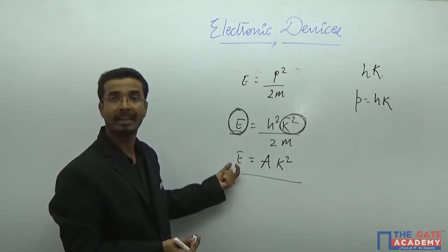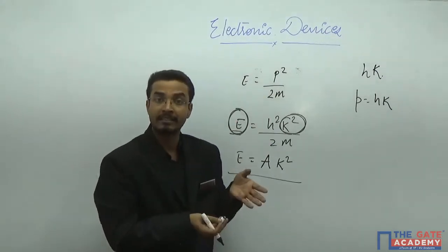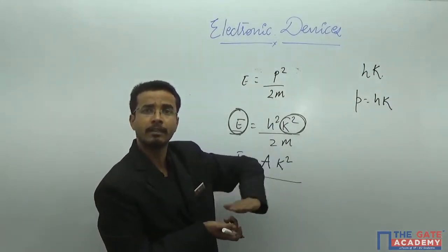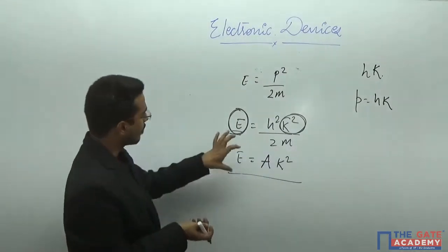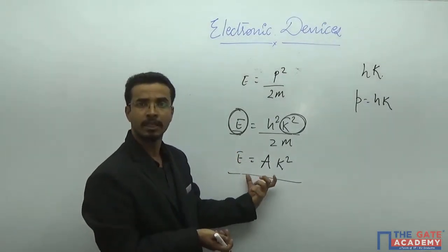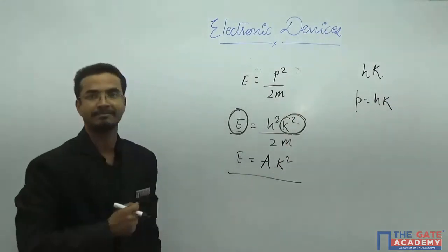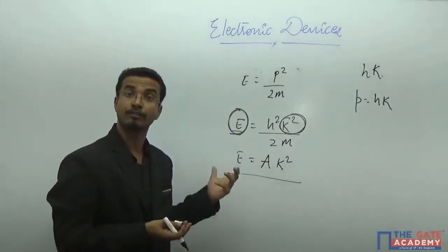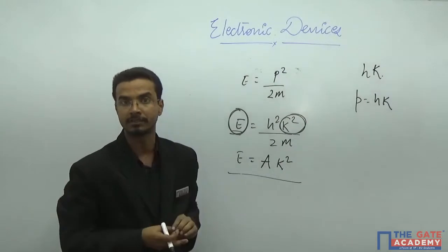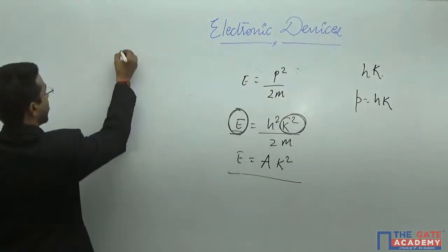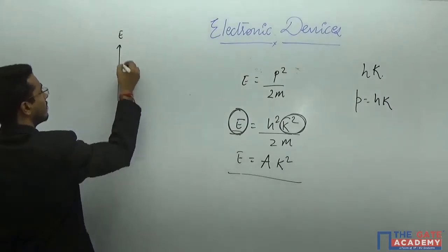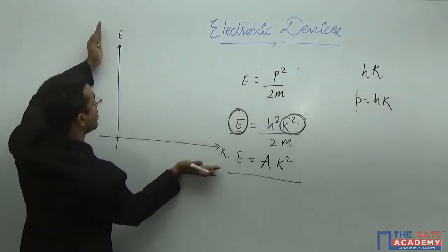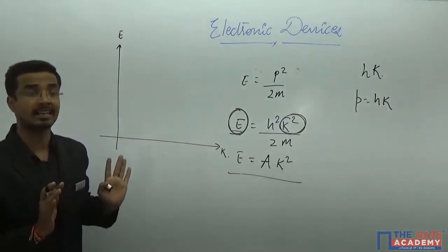Okay, whenever we plot these things in one plane where k is my independent variable and energy is my dependent variable, because in the entire energy band diagram we have discussed that energy always will be on the vertical axis and all the remaining things will be on the horizontal axis. So here also we will extend this particular diagram, and that diagram is known as the EK diagram. That means energy versus momentum. A little bit later you will see the importance of this in describing recombinations. So whenever we discuss this, I will tell that this axis is E and this momentum is K. Okay, so whatever diagram you draw here is known as the EK diagram.